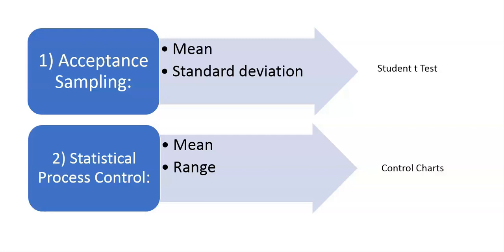In the first method, you measure the length of 7 random rods from 2 boxes. Then you're gonna calculate the mean and standard deviation of those 7 parts. Using this data, you're gonna evaluate student t-test. Student t-test is basically a method that allows you to decide whether to reject or not reject a sample. It is not enough criteria to accept a sample, but in this experiment we're going to accept a sample if the sample meets this criteria, the criteria of a student t-test.